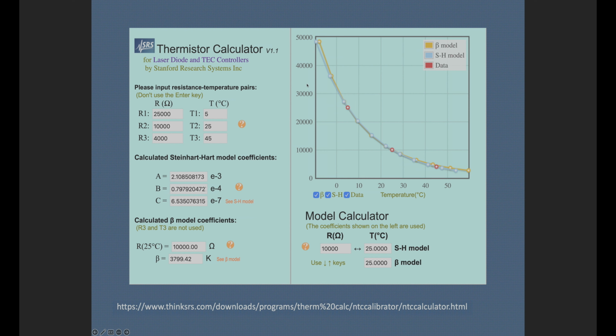Okay, we're ready to go with our temperatures and resistances. We have our resistances all plotted out against temperature here, and we're going to go with the epoxy sensor first and then move on to the Honda sensor second. So here's what we're going to go with for starting out. We're going to put those into an equation. We have 3 accurate measurements at precise temperatures. We're going to put them into each equation. We have an equation for each of the 3 temperatures.